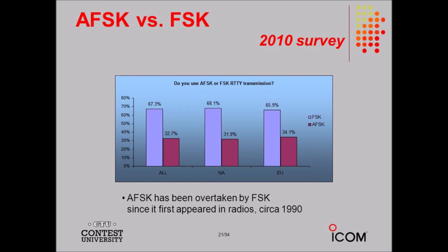And going back to page 436 at the bottom, there's diagram 25.6, which is a block diagram of a basic SSB transmitter. On the left there's an oscillator, then it goes to a balanced modulator. Below that is an audio amplifier attached to a microphone. Okay, going up again to the balanced modulator, you've got a filter, an amplifier, a power amplifier, and an antenna.